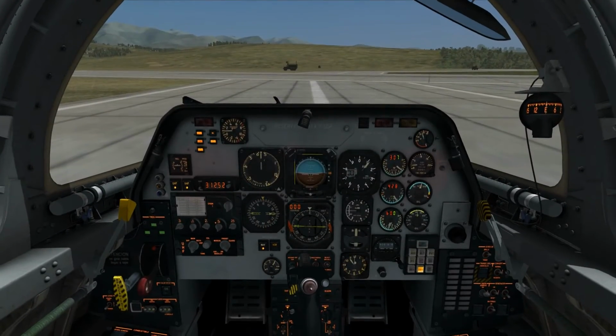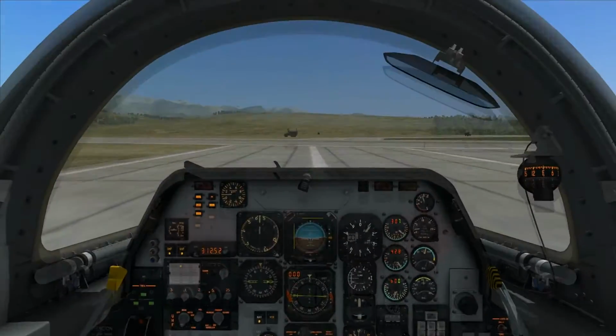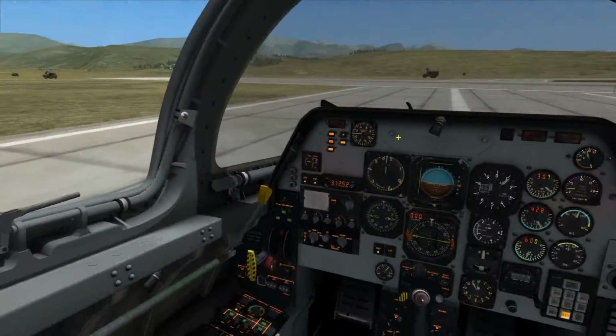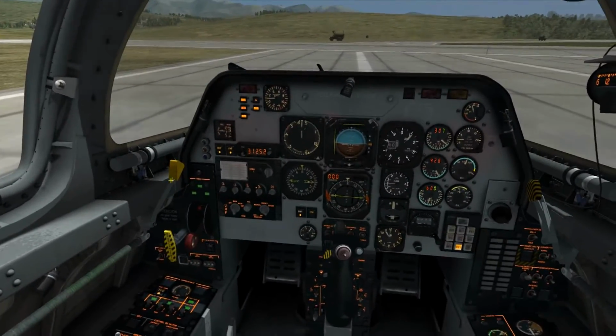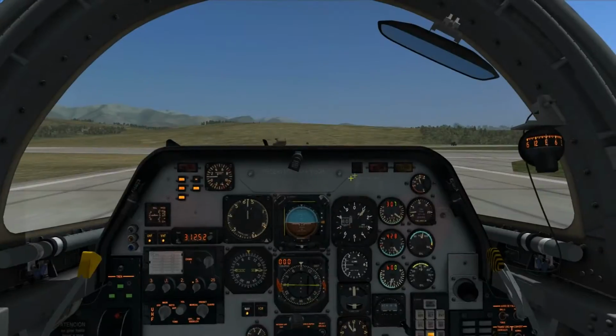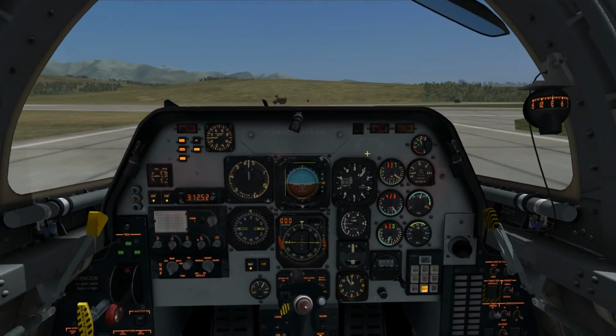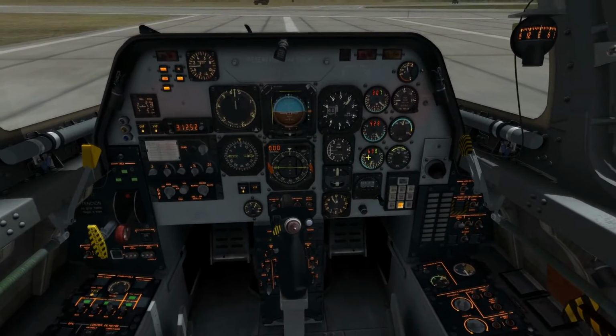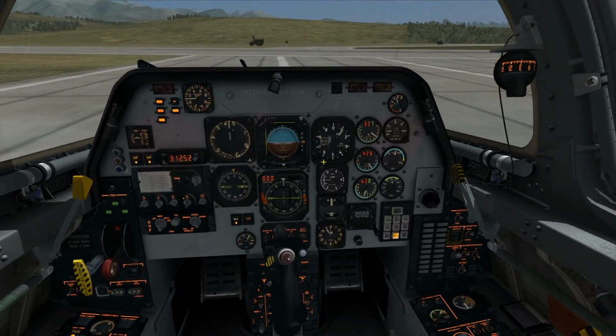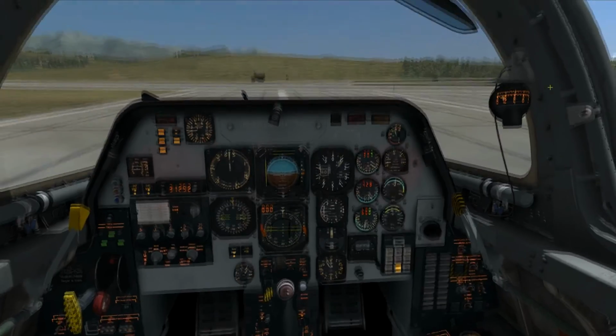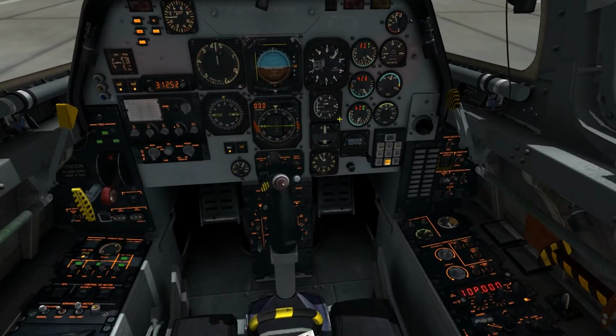Now go for before entering runway checklist. Canopy, check closed and locked. Anti-skid, test and on. The anti-skid is this button. Test now is off. We leave it on position. Altimeter, check QNH, standard QNH. So this is the altitude of the airfield, 110 feet. Pitot head, on.